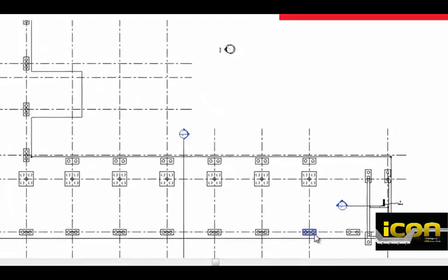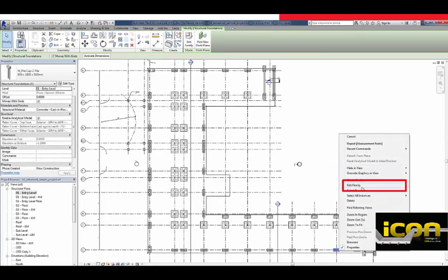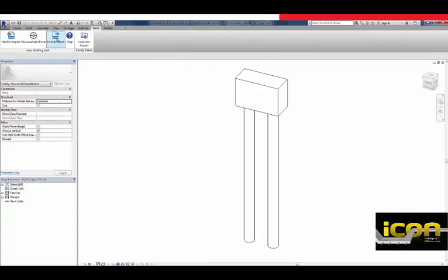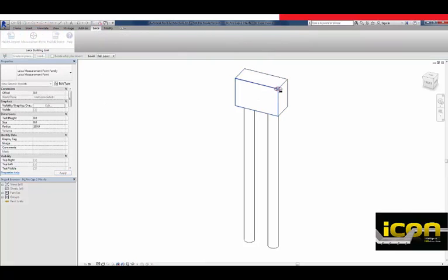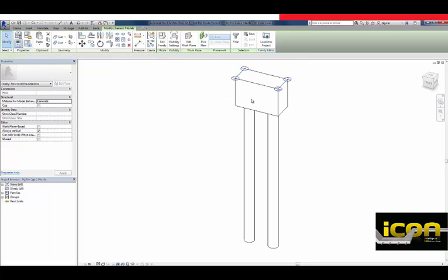In addition to the control points, I will stake out points from a mixture of 2 and 4 pile caps. These points can be generated automatically using the family function of the BIMLink. With this method, it is not necessary to manually pick each corner of the pile cap, as we've done for the floor corners. Simply measure one sample, and then the points for all the other similar objects in the model will get created automatically.